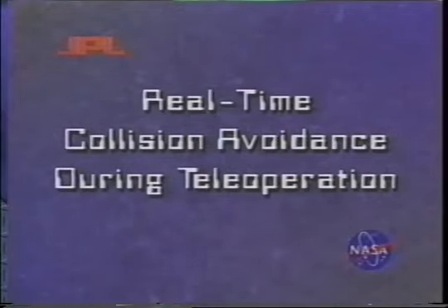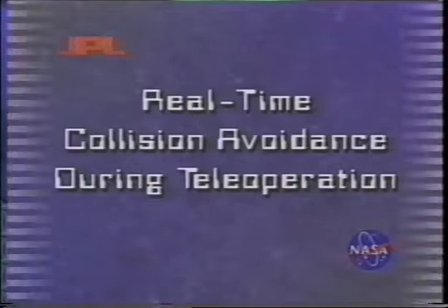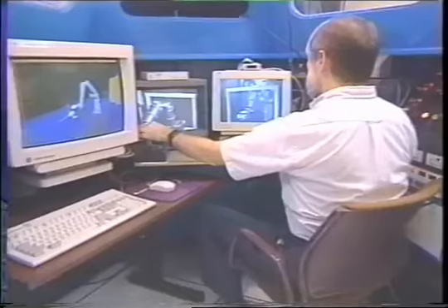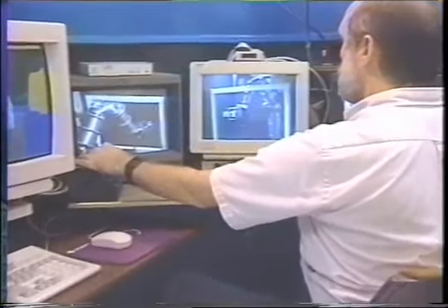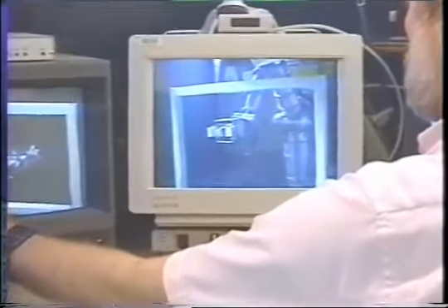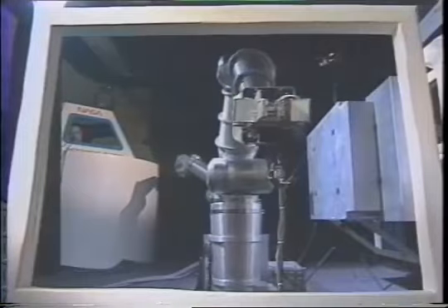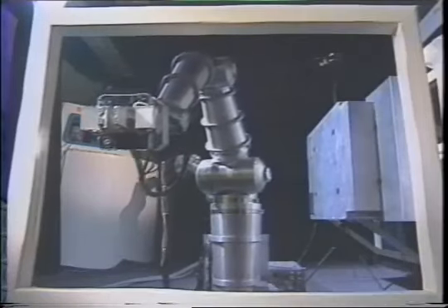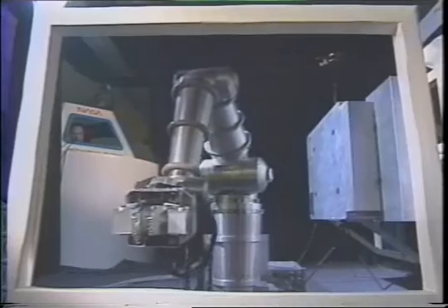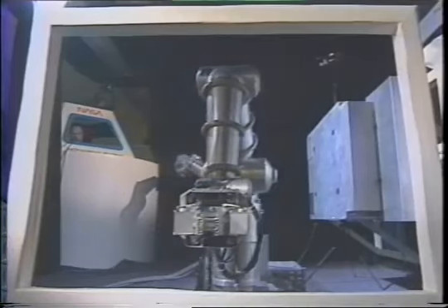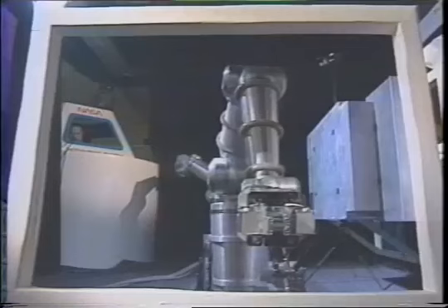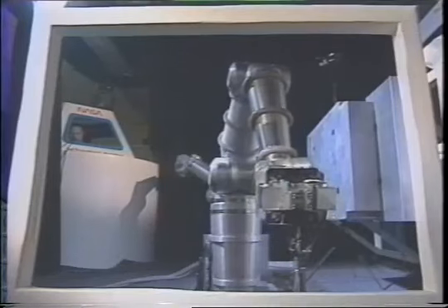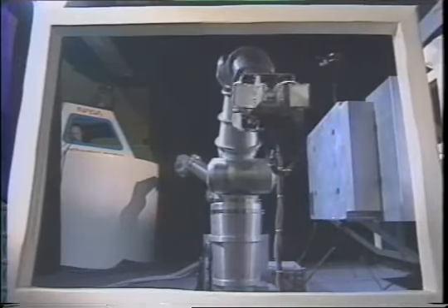Position, orientation, and elbow collision avoidance may be activated or deactivated in any combination and apply equally to autonomous sequence execution and to teleoperation. In this experiment, the user is teleoperating the robotic arm within the truss opening. As soon as the end effector gets close to a side of the opening, a repulsive force is generated in the software which impedes the teleoperation command and inhibits motion toward the truss. The real-time online nature of the avoidance capability allows teleoperation with no prior trajectory planning or simulation.